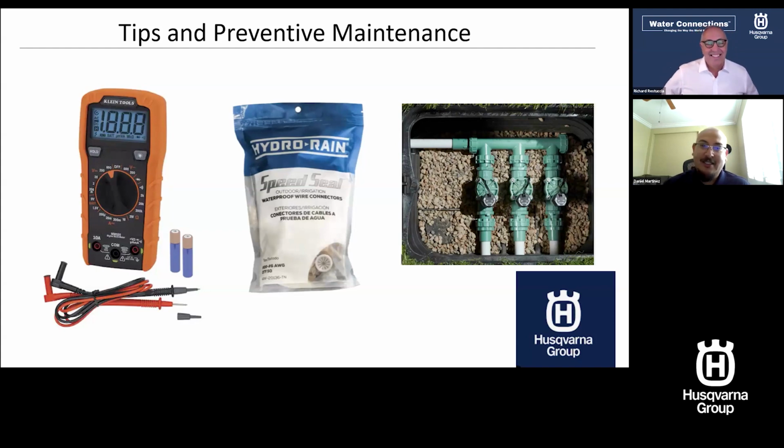Did you diagnose it? Some of these valves nowadays can get kind of pricey. It's a lot easier to just do the troubleshooting, and before you open that up, you've got to shut your water off. You've got water running, you might be getting wet. Test the solenoid with your meter.